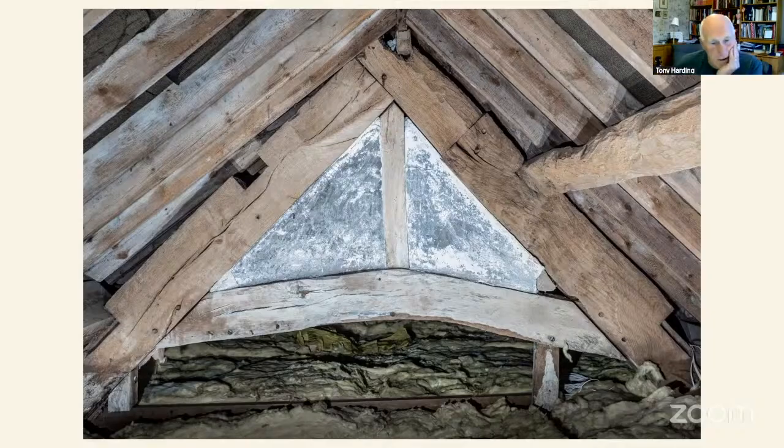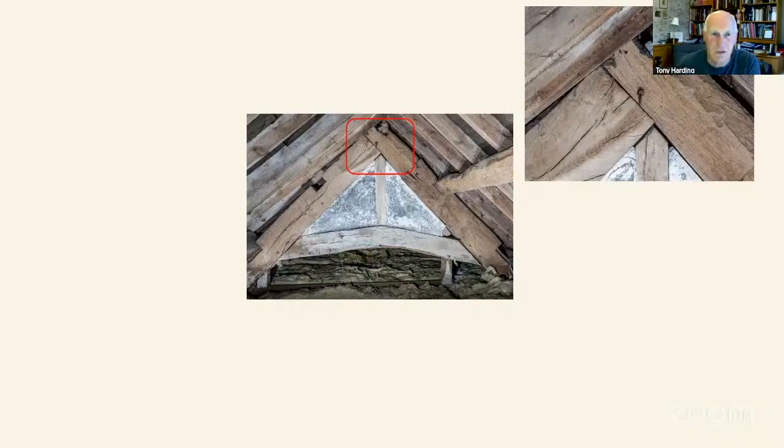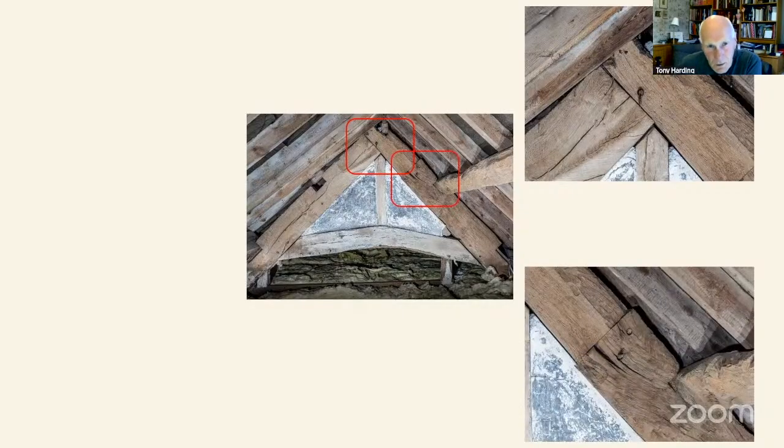But general approach here, in the interest of quickness, is I'll take a general shot of that truss and make sure I get a good quality high resolution shot. And I can usually afford then to take some crops from that same image and get a nice detailed view of the key features we're interested in. The apex of trusses is always of interest to us. This case is unusual. There's a sort of joint here halfway up this rafter, probably because the carpenter that was making that ran out of timber and had to join two bits together.